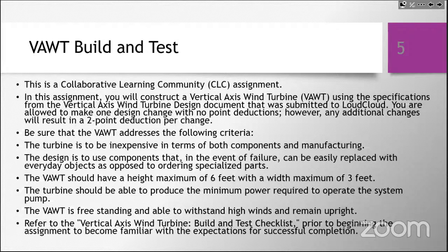Okay, so when we do our test, we have little boxes that these shafts go into, right? We have a nice coupler for them, and that's connected to a generator, and we can see how many volts you're producing. Then you can determine how much power that is. The way you're going to go about this is you're going to assume that if your tabletop model is like 10 times smaller than your real life one, that you require 10 times less power, right? We're going to assume that it scales linearly.